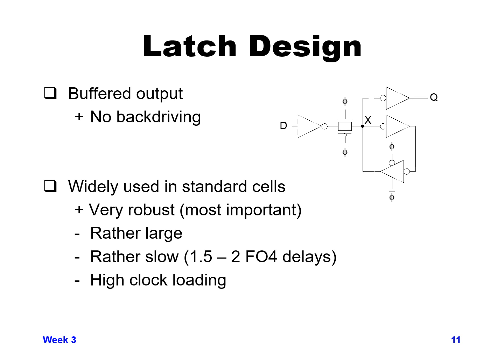For this reason, this standard cell is widely used in the industry in standard cells. For the main reason, it's very robust. You can use it pretty much in any sort of circumstance you want. For whatever driver might be driving into it, it's tolerant of lots of different drive strengths. For whatever thing you might want to drive out of it, it's tolerant to lots of noise, and so it's fairly robust to use in any circumstance.